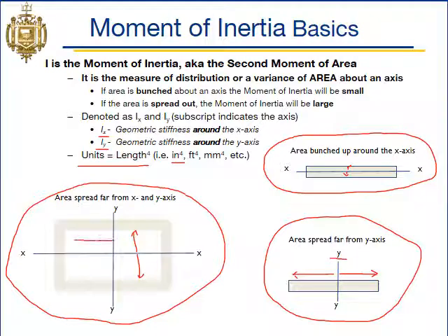And pretty far away from the y-axis. So our thin-walled shapes here would end up with a pretty high moment of inertia. And we can also see that putting area in this middle area here is not going to add a lot of area away from our axes. So we see that the middle area doesn't add a lot of stiffness, geometric stiffness, to our object.